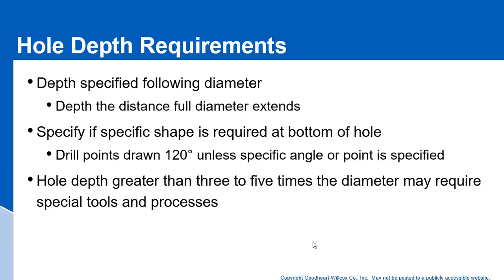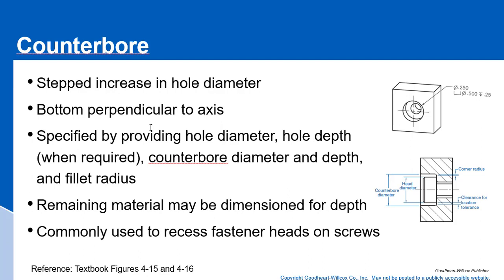We're continuing with the second movie in chapter 4. We're going to start here with the counterbore requirements. A counterbore is a stepped increase in hole diameter like we're showing right here. The bottom of this hole is perpendicular to the axis, specified by providing a hole diameter,